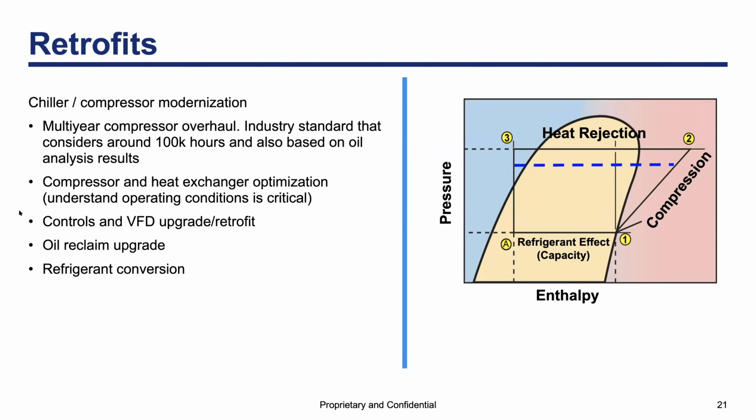When we switch R12 to R134a, the polytropic head is increased, and as a result, the brake horsepower is increased, and the net result is the overall compressor efficiency decreases. So the main idea here with all this is to reduce the compressor energy and improve the way heat is being rejected to the atmosphere through the condenser. The result is an increase in the net refrigerant effect and efficiency, and this is basically what the cartoon states in this slide.